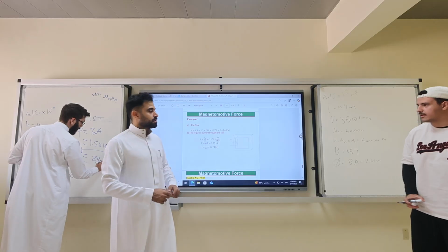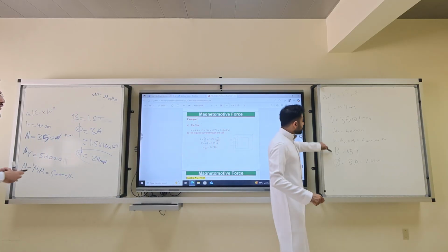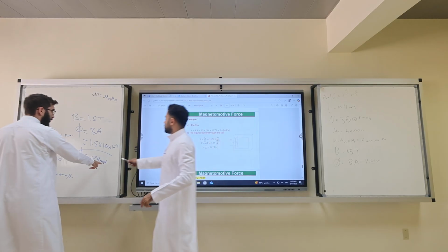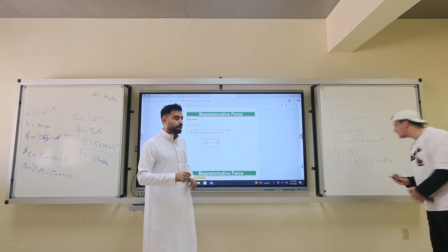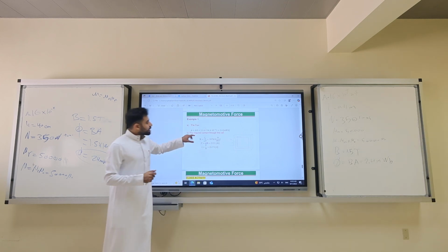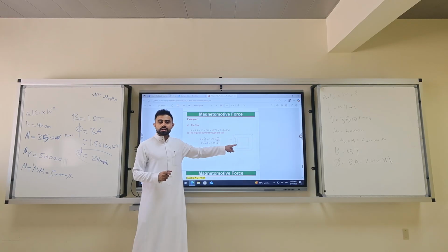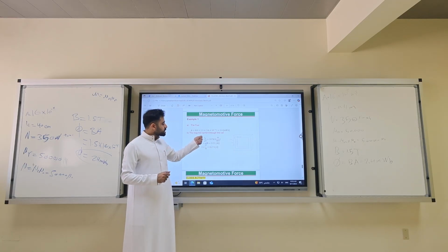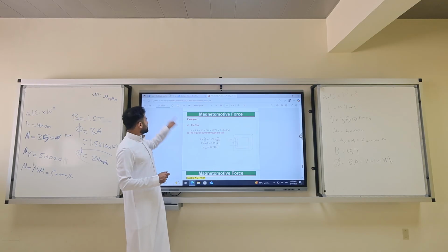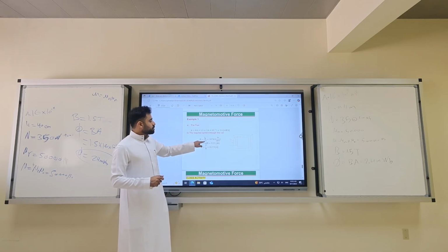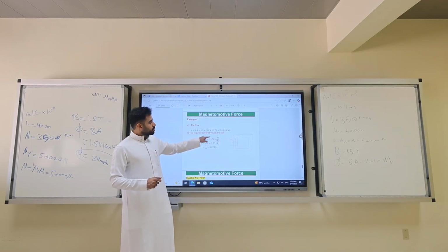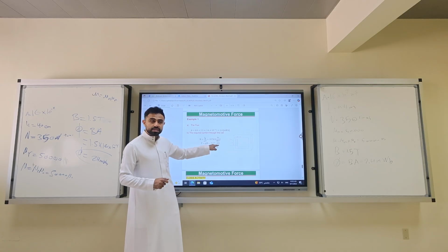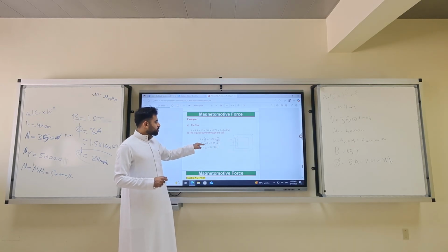Okay, you can have a seat. So, what is the lesson learned? You have to list. Study this lecture today. It is hard. The second part, I want to get the current in the coil. How to get the current in the coil? I have to get the reluctance, which is LC, effective, over mu times A. And then you get the MMF, which is phi, 2.4 milli times R. You should get this number. And to get the current is MMF over number of turns. What's the unit of the current?